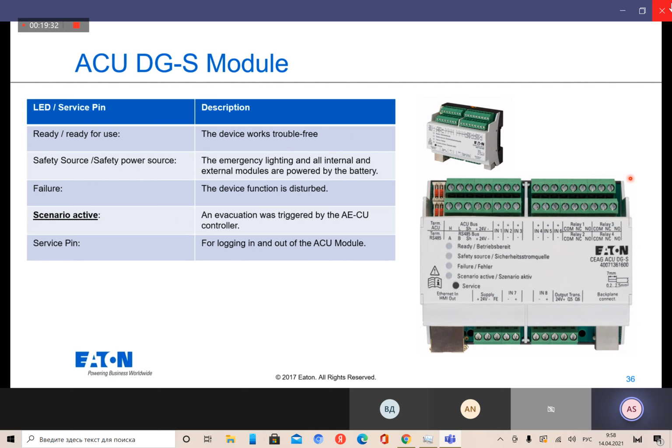Next to it, we have our relay outputs. I don't need to cover this, I think. You can connect the F3 interface to it. You can connect your building management system to it, whatever you want. You can freely program and assign them. What's new is that each relay has its own COM contact. So now we have absolutely separated relays. We don't have the C0 contact you might know from the ZBS technology. Okay.